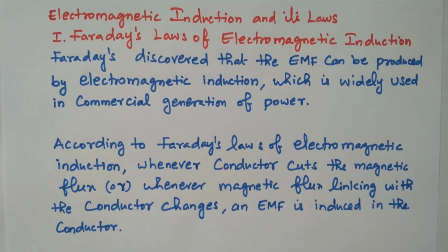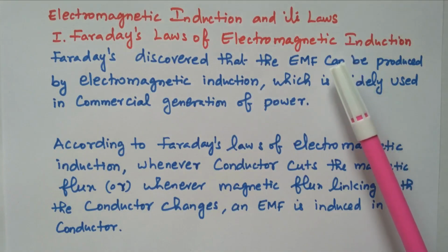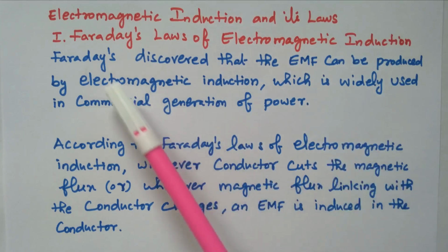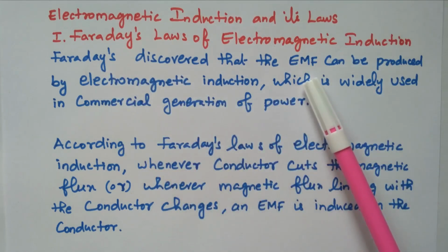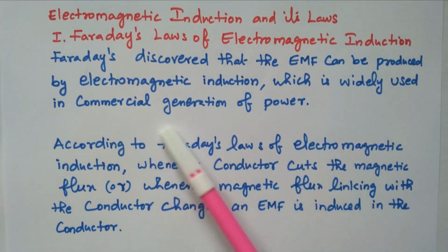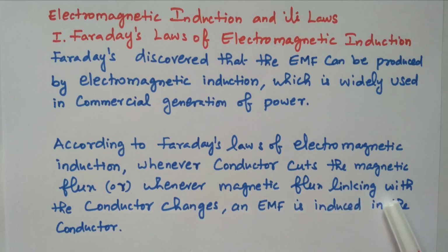Welcome viewers. In this video we will see electromagnetic induction and its laws. First we will see Faraday's law of electromagnetic induction. Faraday discovered that an EMF is produced in electromagnetic induction, which is widely used in the commercial generation of power. Based on Faraday's law, whenever a conductor cuts the magnetic flux or whenever the magnetic flux linkage with the conductor changes, an EMF is induced in the circuit, in the conductor.